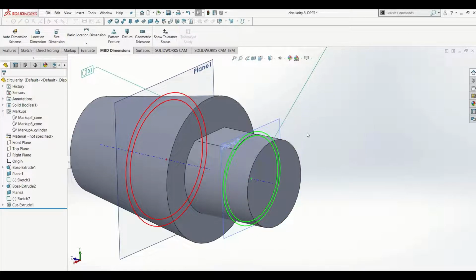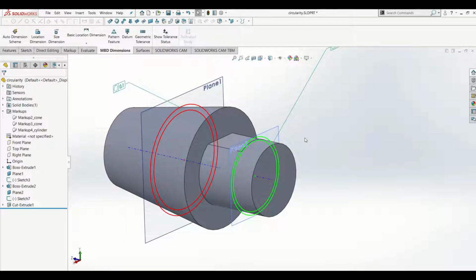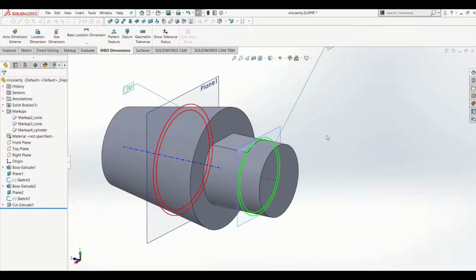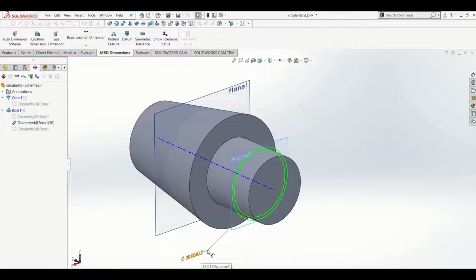That's why during the measurements, when we put the part on the turntable or the V-block, we will place the digital dial in a few more cross sections. Yes, it is not practical or possible to place it in every cross section, but it is the usual practice or the problem in roundness measurements. Now we learn about the basics of roundness tolerance.